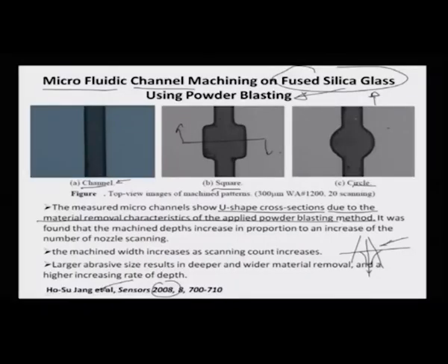So typically that is what is reflected here also in terms of the abrasive jet machining process. And you can see that the machined depths increase in proportion to the number of nozzle scans.